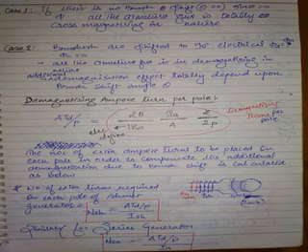This is not the process which you are doing after the machine design. This is done before the machine design itself. You will be calculating the brush shift, everything, and if 5 turns produce 5 Webers normally, due to brush shift some additional demagnetizing you have to calculate, and while designing itself, you have to extend the number of turns to that value. So let us consider these are N_SH extra turns. These turns are some extra turns to compensate the demagnetizing effect. So what will be the current flowing in these extra turns? Same current, I_SH only. If I_SH flows in these turns, all are in series. In this also I_SH will flow.